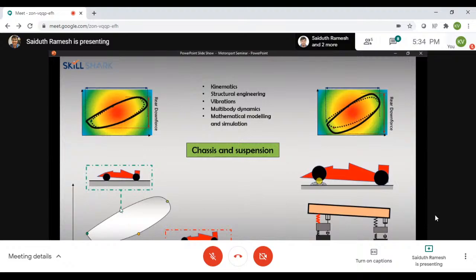This is where the pitch is relevant. If you can see here, the car is at a point where it's accelerating. When you accelerate in your car, you get thrown backwards because of inertia of rest. That's what happens in any situation. The whole car actually jacks backwards, and it transfers load to the back. When you hit the brakes, as you can see in this red zone over here, the car pitches forward.